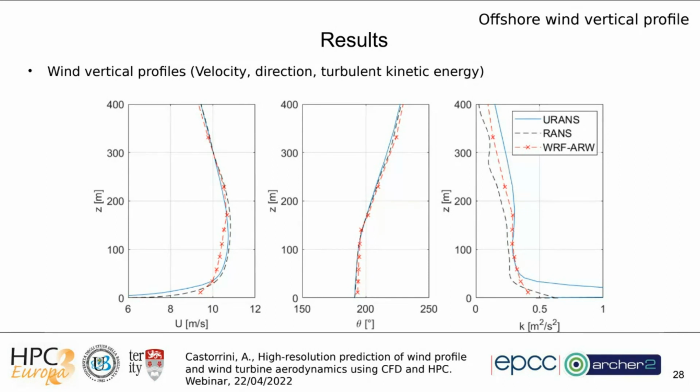And you see also from the plot on the right that the turbulence due to the presence of the waves is increasing in the first 50 meters, more or less. But also with this technique, we can obtain a wind that can vary its direction along the elevation in the domain, which is not possible, for example, with the theoretical models and the standard ones.